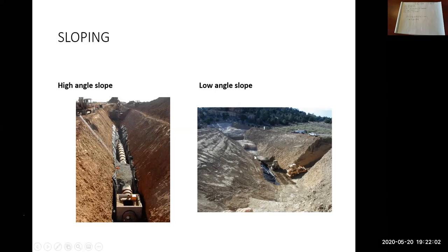But obviously this excavated volume with this flatter slope is quite a bit higher than this excavated volume with the steeper slope. And we saw that in the review of exercise 5. The steepness of your cut slopes significantly affects the volume of excavation that you have.